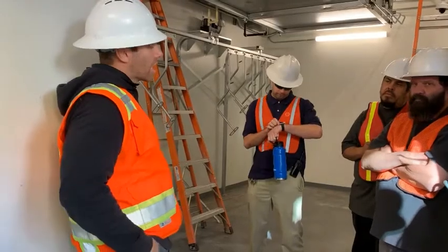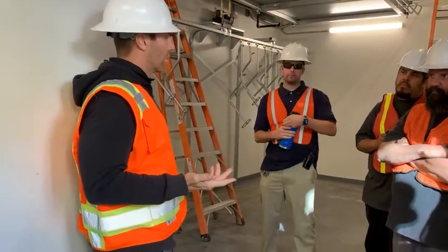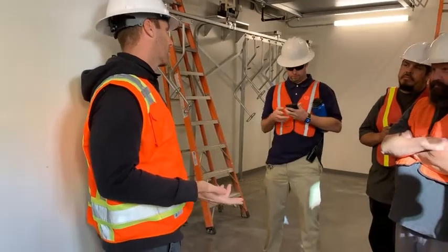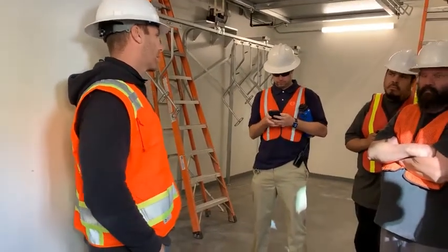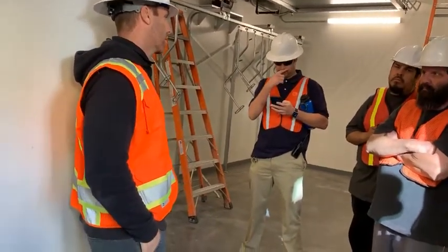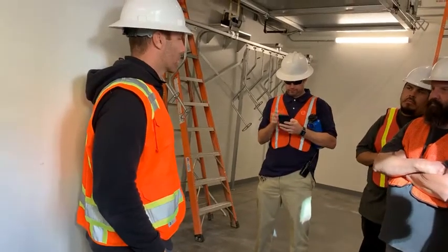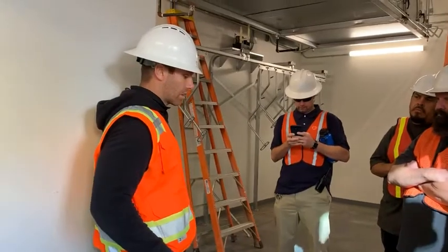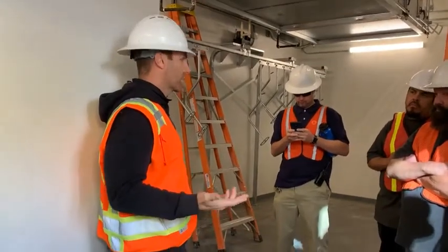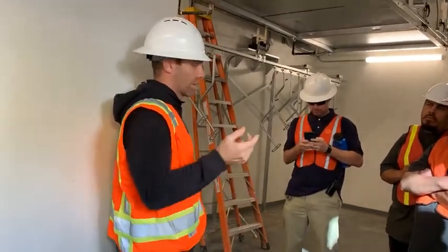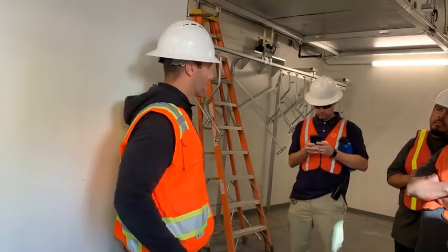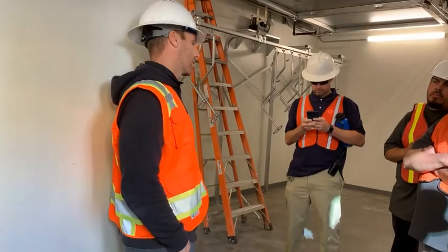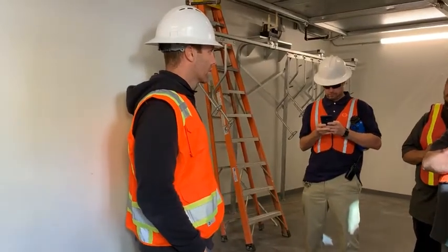Think ballast and bulb. It's really no different. It's just dimmable and using a different technology, but your troubleshooting really shouldn't be any different. You go to a full fluorescent fixture and half the fixture's out, you change that bulb. A lot of times it brings up the other bulb, and that bulb's good now. And if the whole fixture's out, typically it's probably the ballast.